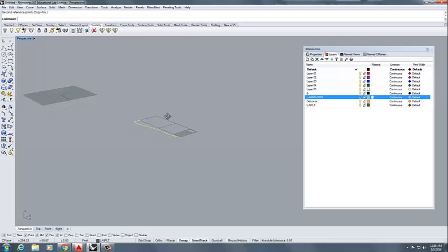I need to change my construction plane. So the second tab over is C-planes. As a visible thing, it's nice to see this little grid to show how the construction planes work. For all intents and purposes, I might as well move all of my line work over. It doesn't have to hit this spot. We're not working on an exact model that needs to magically hit this spot.